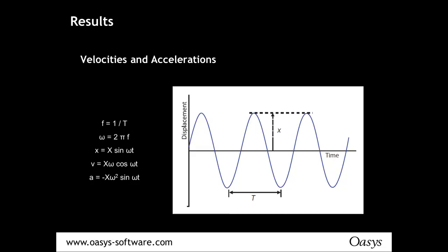So we found the vibration modes. Now we need to do a response analysis, a subsequent analysis, to calculate the velocities and accelerations, and thus response values on the floor. Now, these velocities, you might be required to calculate in terms of peak velocities, or root mean squared or root mean cubed velocities, depending on the design guide you're using. And similarly, the accelerations might be meters per second squared or percentage g, and so on. Design guides will tell you exactly what values you're looking for.